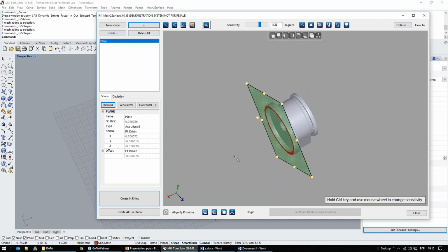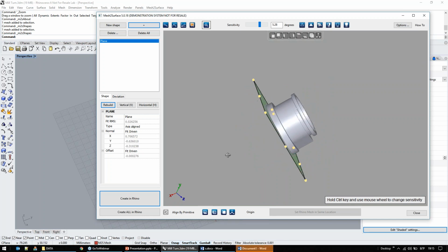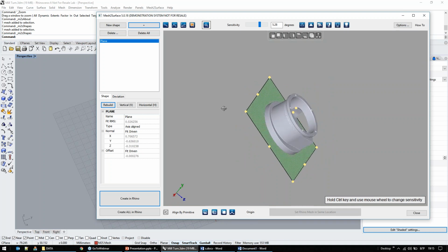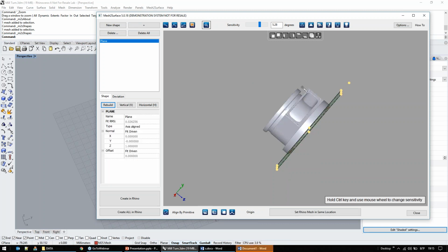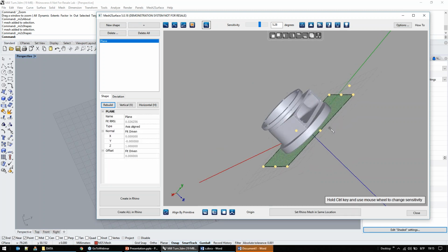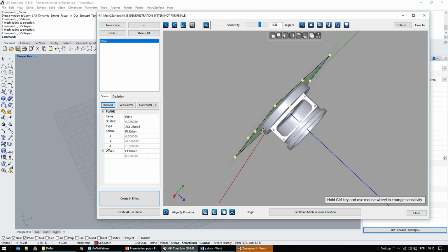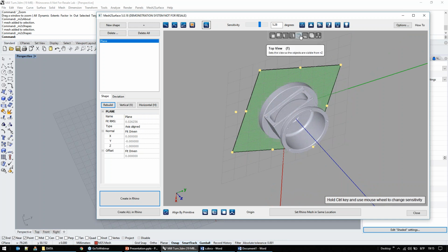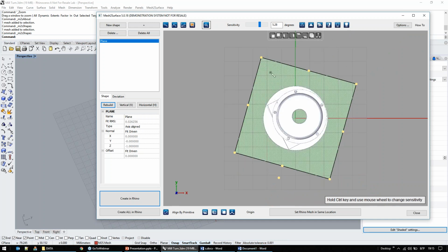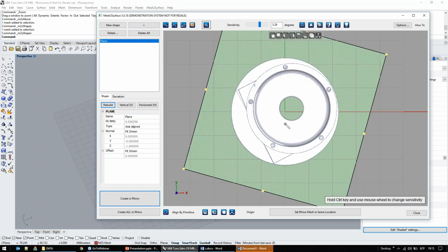Mesh2Surface has some simple tools to align the object in space. We have a couple of commands here, which, based on the current shape you have, you can use to say, okay, I want to align this to my bottom plane, which is in fact the XY plane mathematically. If I take a look, it just aligned. Because the plane has normals, we don't know actually what is the right way to align it. So if I press it twice, it will flip the orientation. And now if I look from the top, I can see that my plane is exactly what I would like.